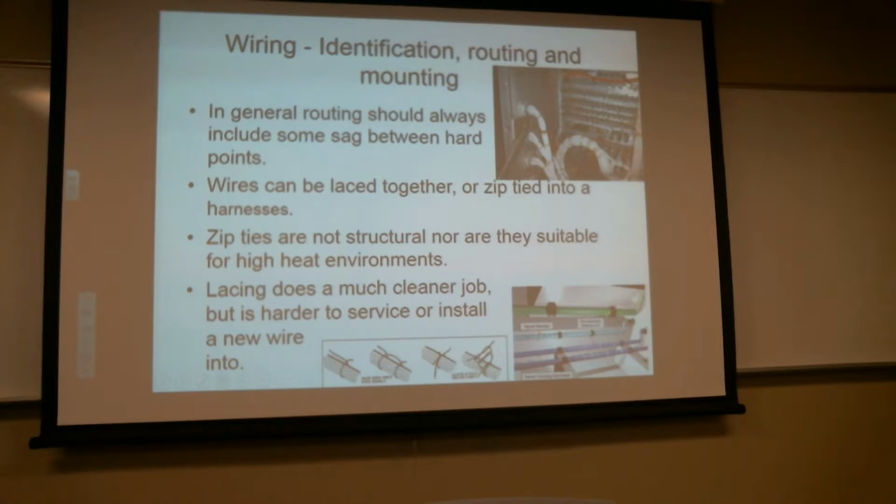Copper doesn't have the greatest amount of thermal expansion. Aluminum has great thermal expansion. So a little bit of sag point just to allow it to shrink and expand, or a service loop, which would be even more.